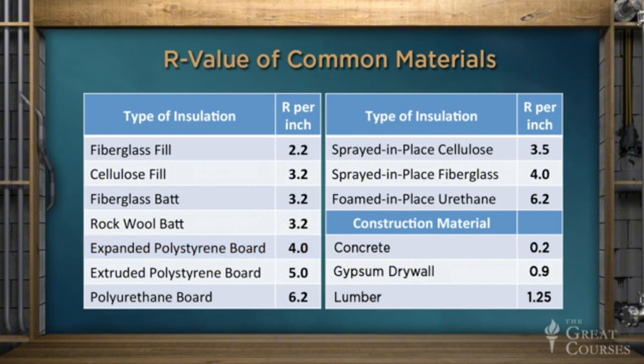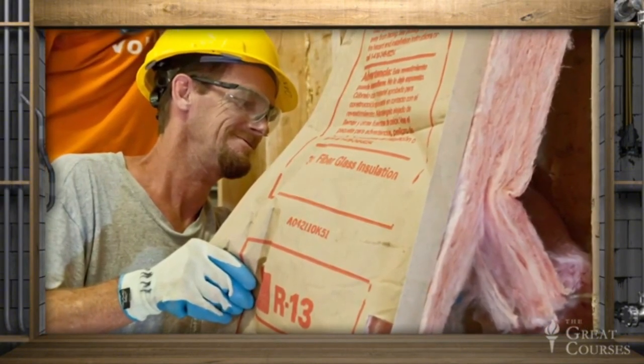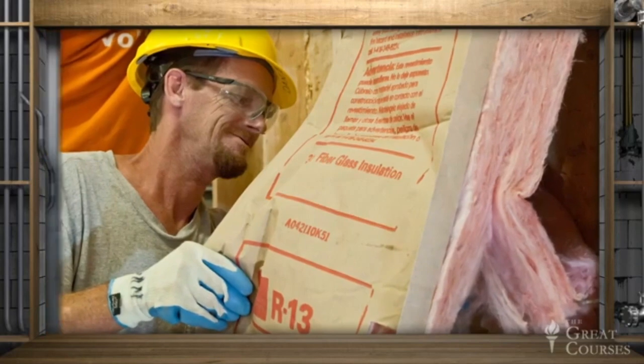Now, several aspects of the data presented in this table warrant further discussion. First, although fiberglass batting remains the most widely used insulation in US residential construction today, there are many available products with superior thermal resistance. Moreover, fiberglass can be significantly less effective than even these R values suggest. Fiberglass is only really effective when it's properly installed.